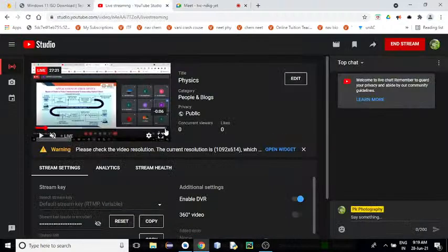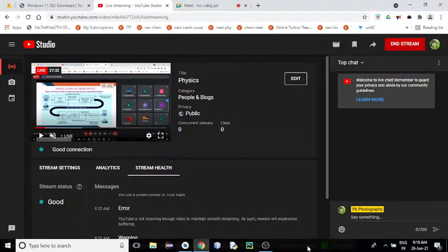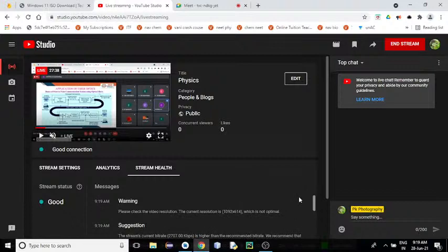So V will be 35.03. Since V is very much greater than 1, the number of modes will be approximately equal to V square by 2. If you do that, you'll get 613.55. So this many light rays can propagate through your fiber. I'll proceed further. Write on the next one.